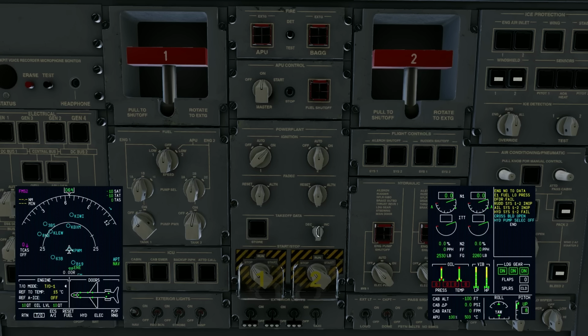Alt TO1 is your standard D rate. So Alt TO1 is a TO1 10% reduced, so 10% thrust reduction. And this is a mode that we use very often because it saves the engine some wear. And that's obviously good for the engine. Rolls-Royce prefers it because they have to do less maintenance, and so there's a lot of incentives in the real-world flying world to not do a full thrust takeoff.